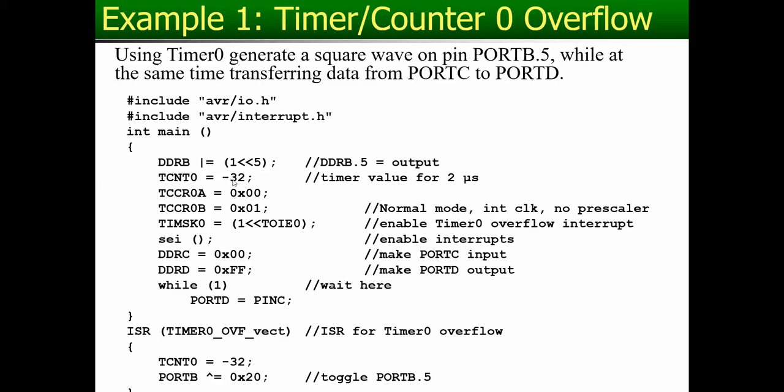You can directly put 224 here. It doesn't matter. And then just normal mode and no prescaler. And then the timer overflow interrupt has to be enabled in TIMSK.